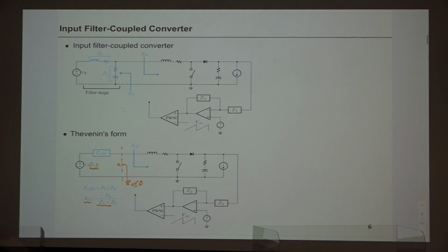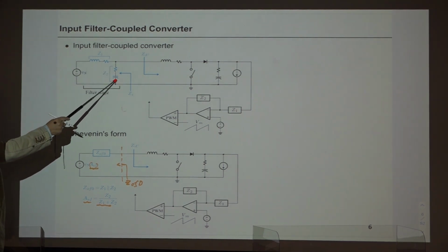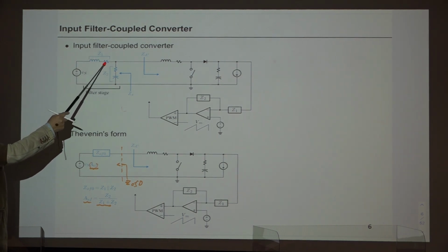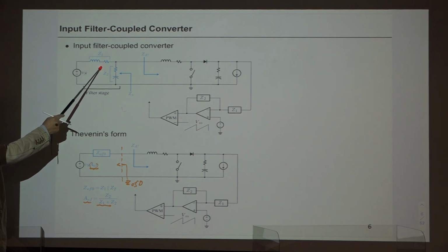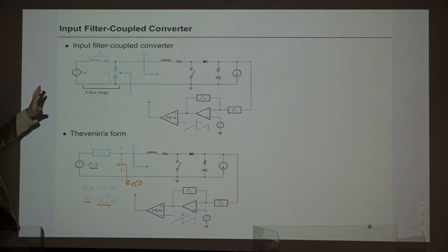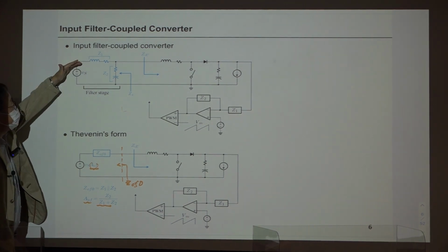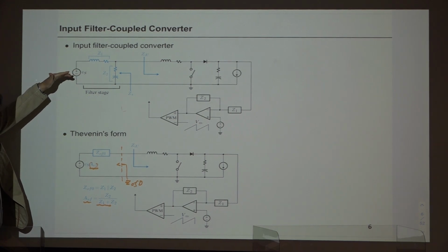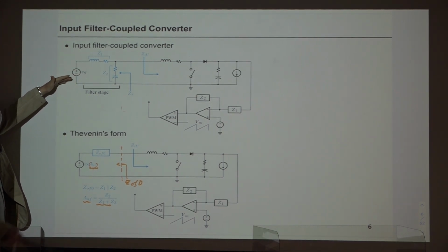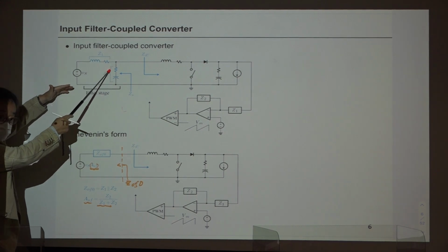All right, another simplification. This is a very simple structure of a single stage LC filter. There are two reactance components. This one is an inductor. This one is a capacitor. The inductive impedance should appear here. Right? The purpose of this is that this G1 branch should present very low impedance to low frequency components, particularly for the DC component. This presents very small resistance.